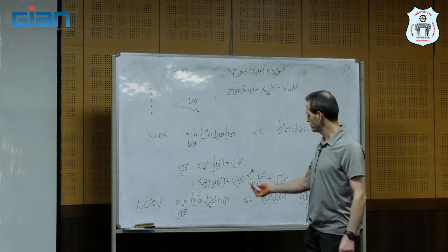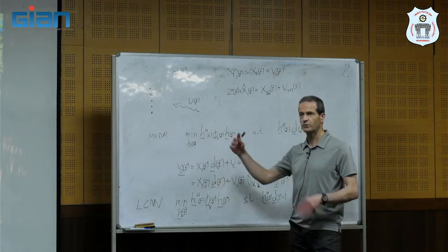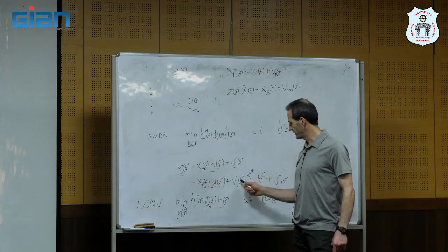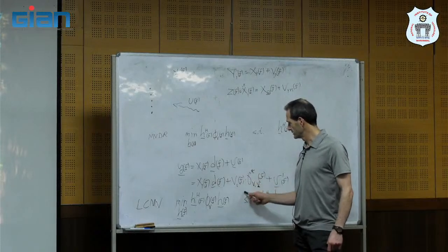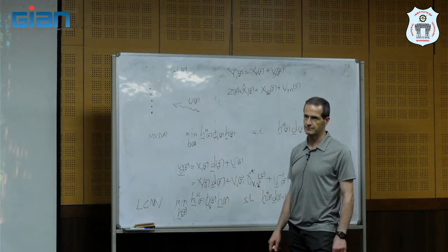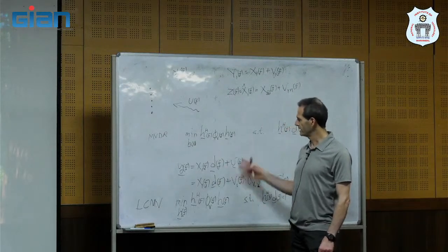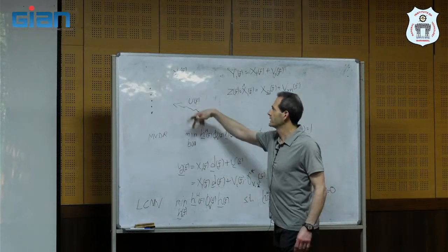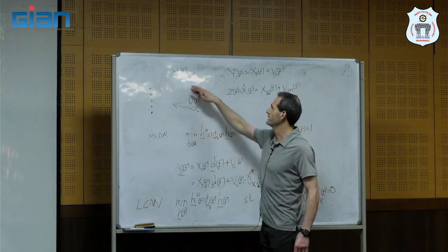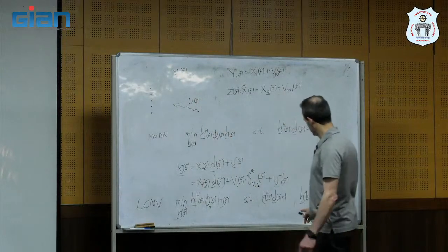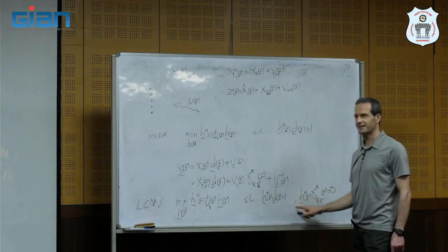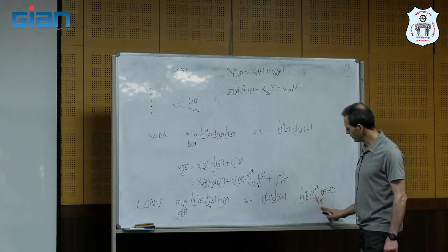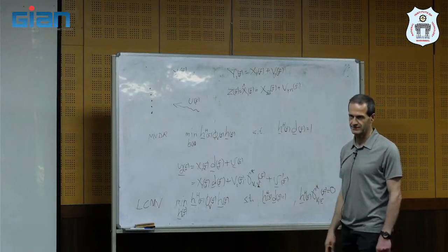Because the steering vector, propagation factor, it depends on the correlation, including all the reflections. So if it's far-field, the desired source and the coherent noise come from the same direction. Okay? So obviously, if they come from the same direction, we are limited there. We cannot reduce one by keeping the other. You see, these two constraints, if this equals this, we cannot satisfy both. We can satisfy both if they come from different directions.